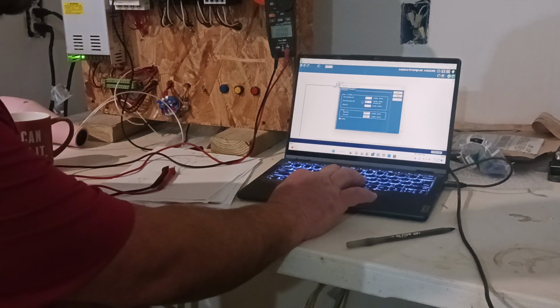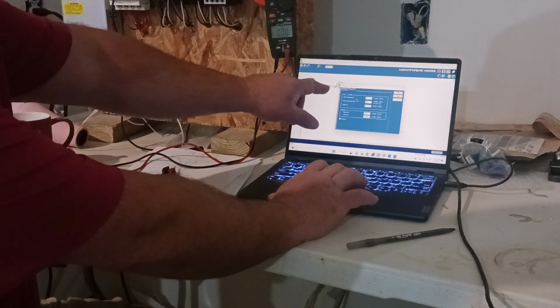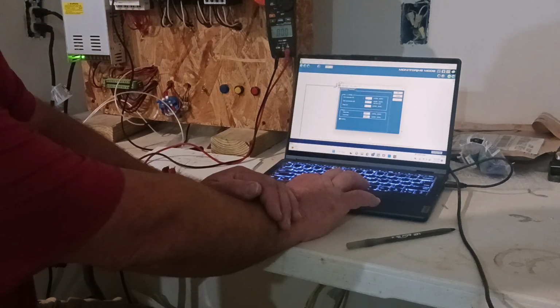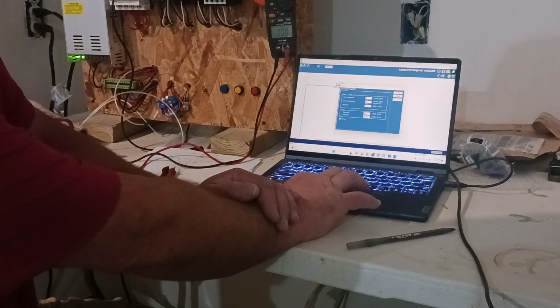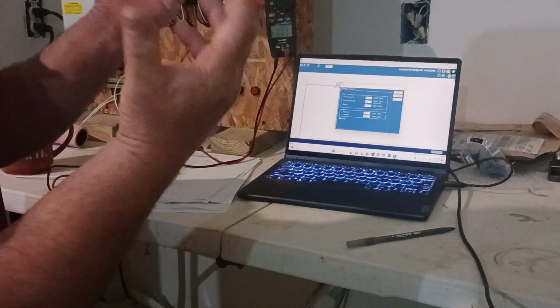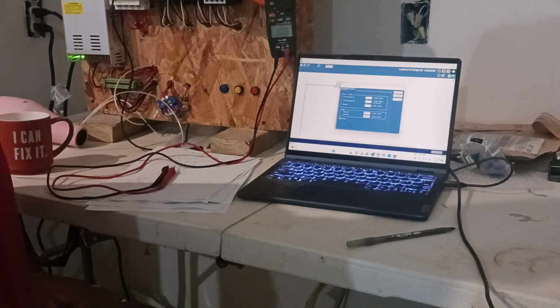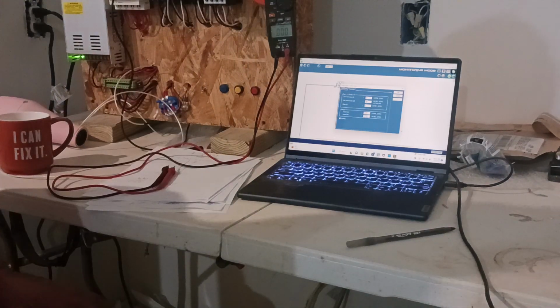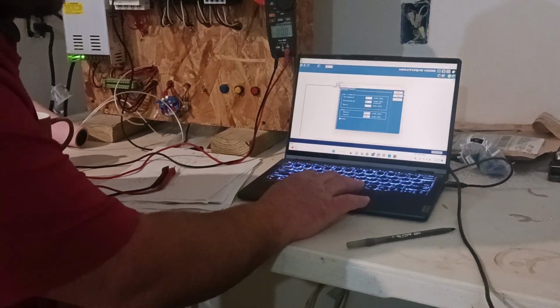My rate of change: when my analog value changes by 1, how do my volts change? Well, 10 divided by 255. You just take the highest number of the voltage and the highest number of the analog value, and that's pretty much your rate of change.